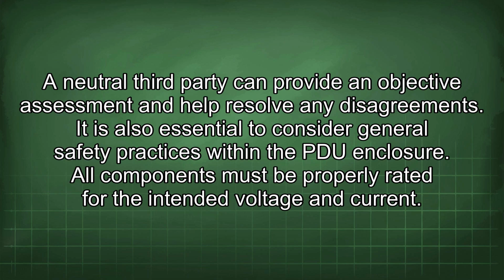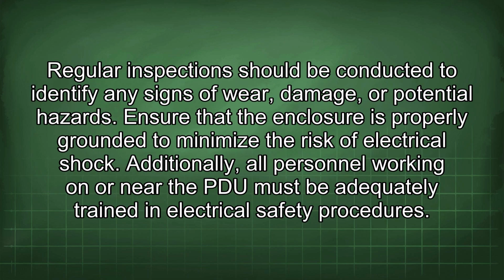It is also essential to consider general safety practices within the PDU enclosure. All components must be properly rated for the intended voltage and current. Regular inspections should be conducted to identify any signs of wear, damage, or potential hazards. Ensure that the enclosure is properly grounded to minimize the risk of electrical shock. Additionally, all personnel working on or near the PDU must be adequately trained in electrical safety procedures.